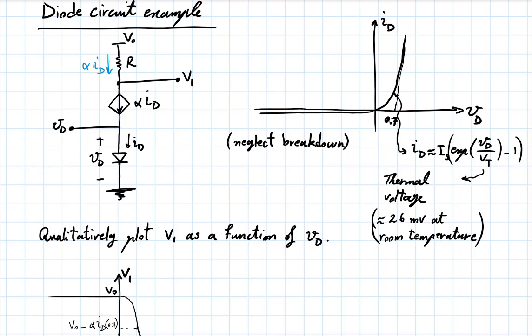But hypothetically, in an ideal world, this diode could take any voltage, right? Even 100,000 volts. The current would be enormous. Calculate the exponential of 100,000 divided by 0.026, and you will have a problem getting the number from a calculator. In practice, of course, you're not going to go beyond 0.7 or 0.8.